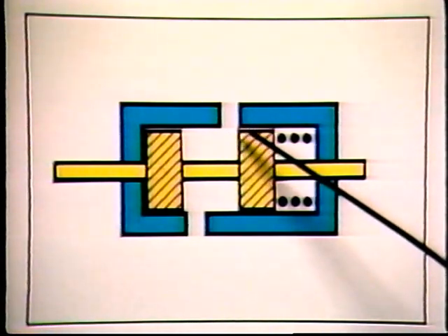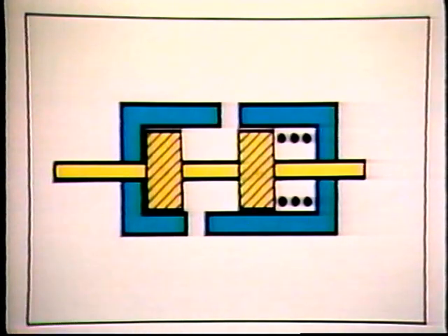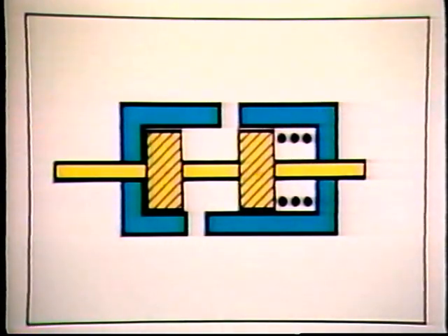The spool shaft extends through the end of the valve body, here. As you see, when the spool is in this position, we have a passage here and here, which allows airflow through the valve. It has a symbol which looks like this, and it indicates that there is airflow through the valve. Okay, that's one function of a two-way valve.